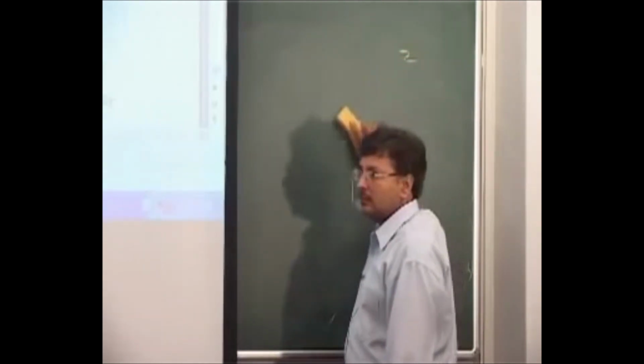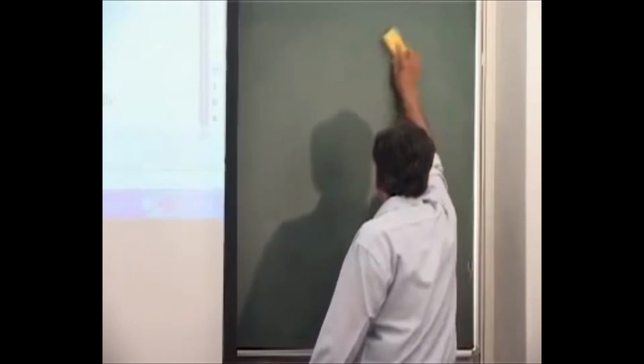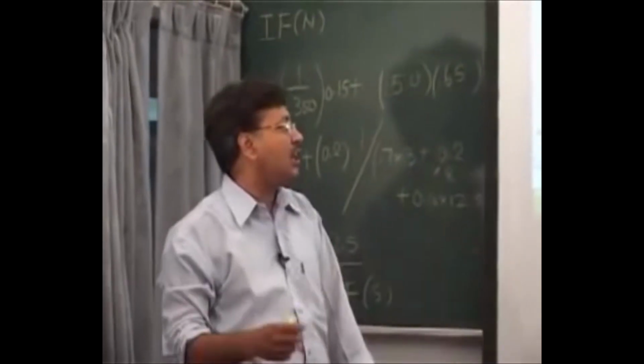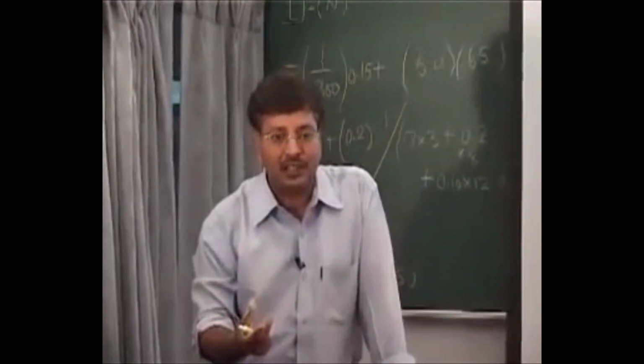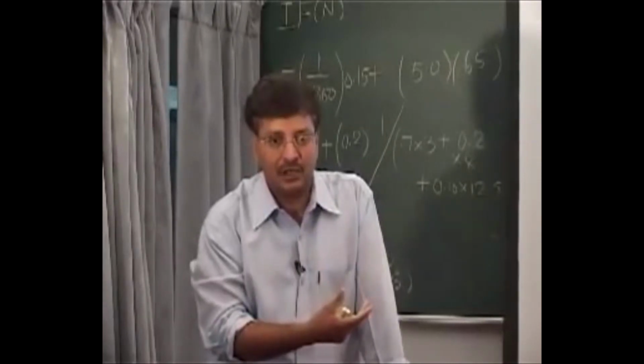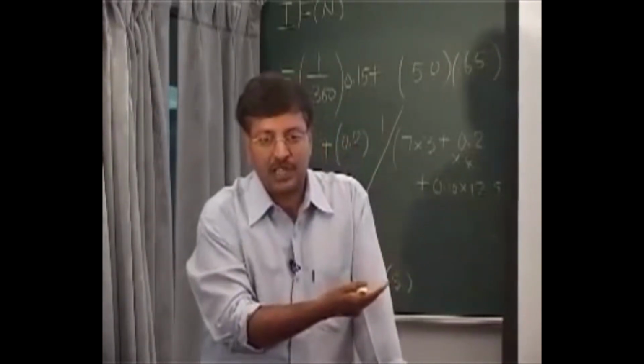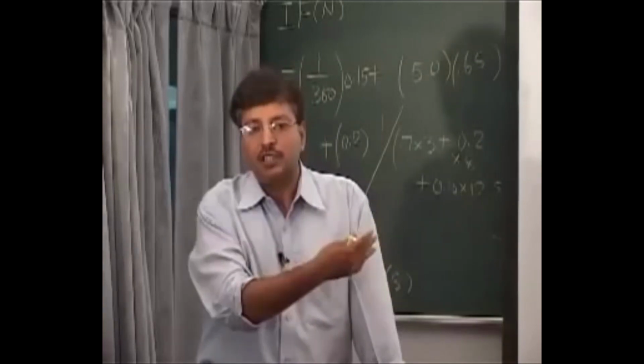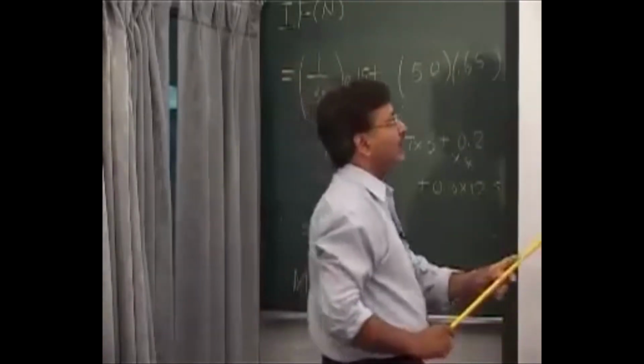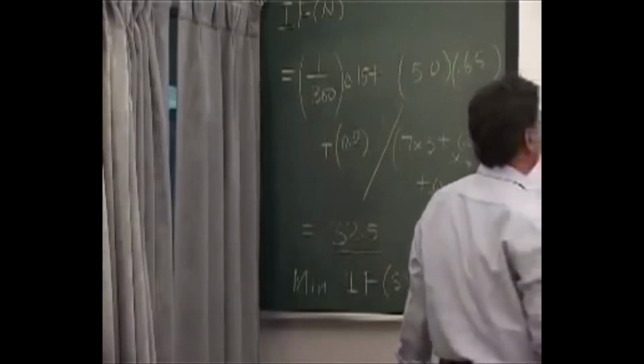Why are we not converting the mixing height here into kilometers? You can convert that too, but unless you have been asked to do that, you take the number the way it is given to you. This factor is dimensionally not correct. It's just arbitrarily decided. Even if you take that in kilometers, your answer will not change because purposefully a lot of weightage is given to 0.65 to the wind direction. That was the idea.